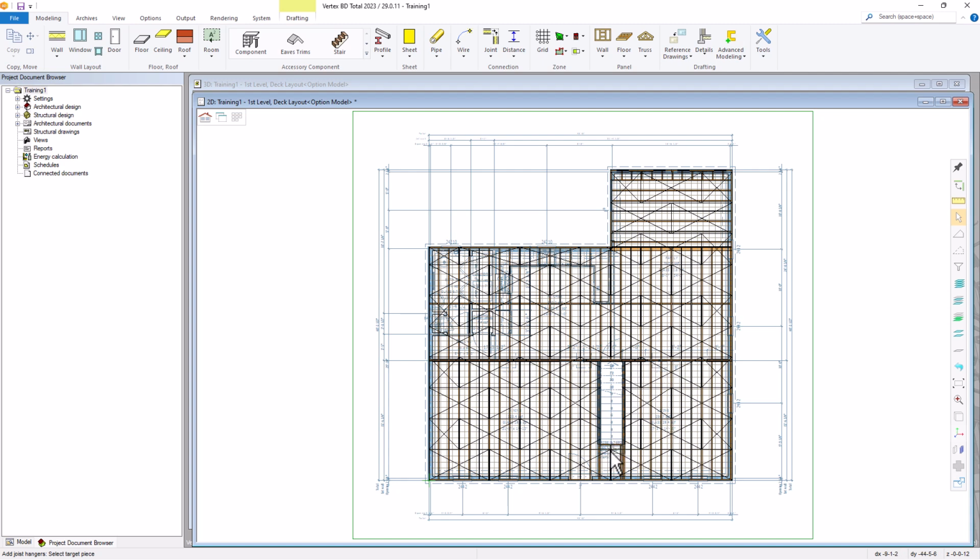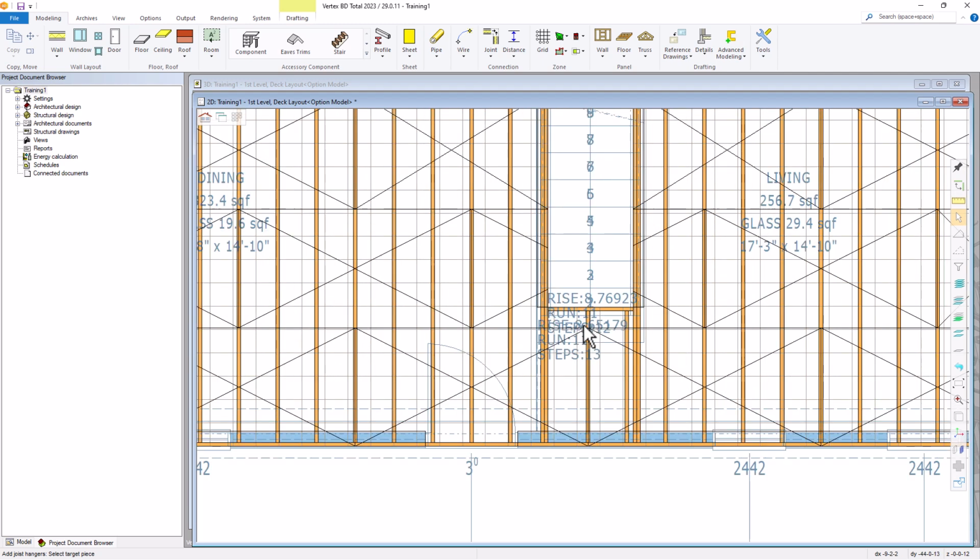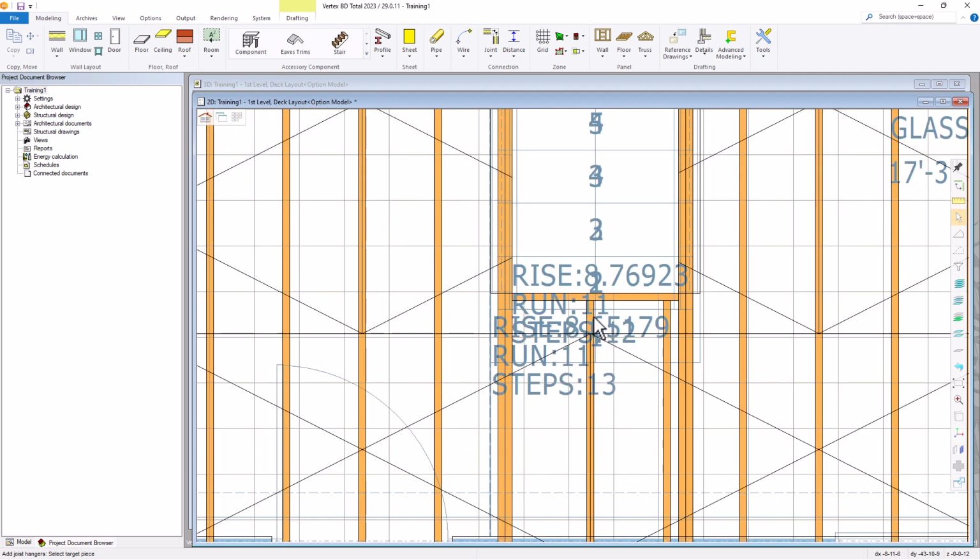Let's go to the stairwell opening and add some hangers there. We'll add these individually. So we'll add a hanger here, so the supporting member is the header piece at the stairwell. And now it prompts us, select connecting piece ends, confirm. That is the joist that is being supported by the hanger. In this case, it'll be this joist. After you make your selection, you'll see a yellow dot indicating the location of the hanger.